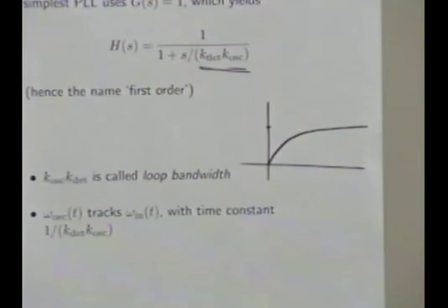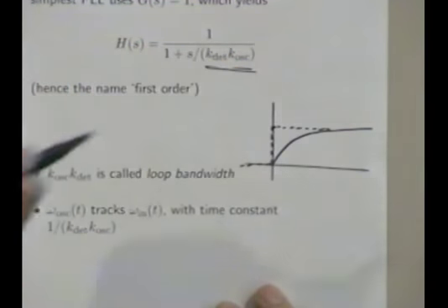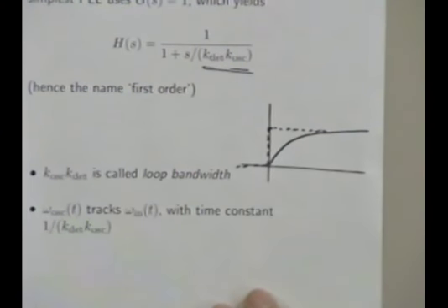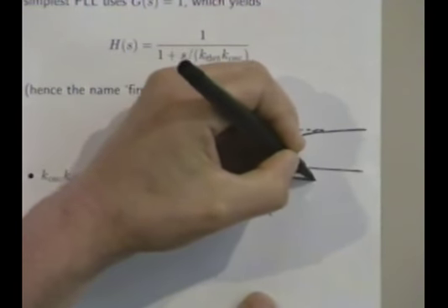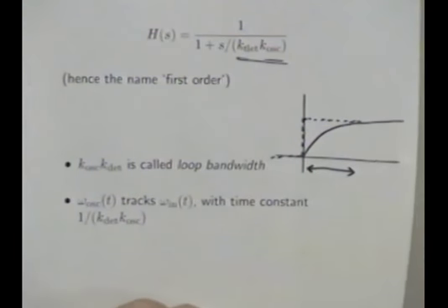So that says if two communication systems are communicating and something happens to the oscillator, like somebody bangs the desk over here and the crystal has some weird dislocation, and the frequency changes rapidly by a small amount, then the frequency at the other end, so if this is the frequency of the transmitter, like that, then the frequency of the receiver will look like that. This time will tell you how long it takes to lock, to reestablish lock. Okay, so that's the idea.